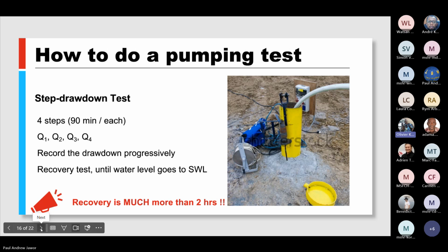If this is not possible, then this can inform us of the kind of aquifer from which we are tapping water. It tells us that the pumping rate is higher than the rate at which the aquifer feeds water back into the borehole. So it can start giving us clues as to whether or not our borehole will be efficient.